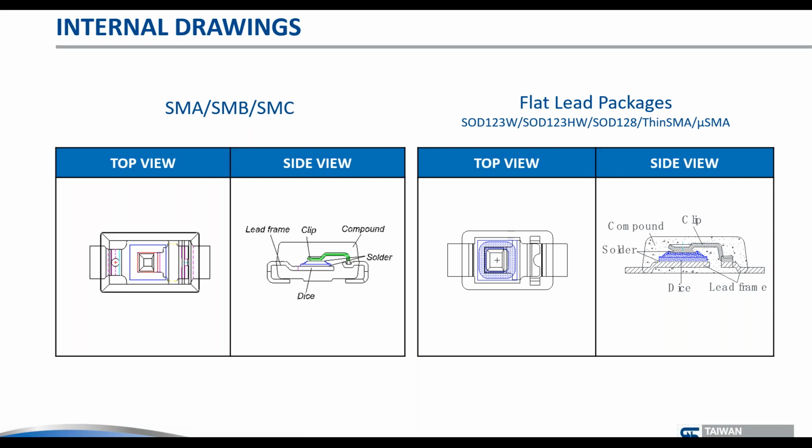They look a little bit more elegant. We're going to see if that really brings you a lot as a designer. But obviously, the path for the heat to get out of the die into the PCB is slightly shorter, and that's what you really want from a thermal perspective. Now, there's only so much you can do because also the width is important in these lead frames. If you make them less wide, then you also increase the thermal resistance. So this is the capability, or how these packages compare.